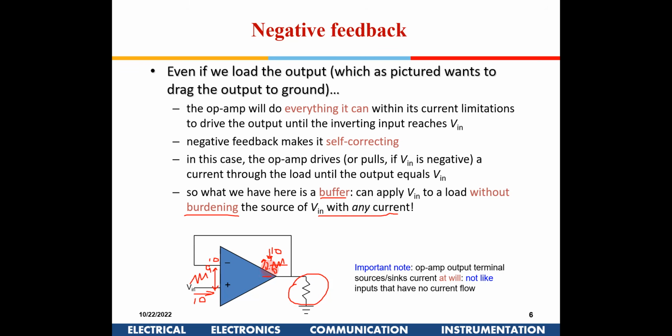But that cannot happen because the moment it starts slightly below, because of the high gain, again it will reach back to 10. So in an equilibrium condition, you can consider that these two voltages will be the same. If it is the same, then the difference is zero. Then the output tries to reach 0, but still the negative feedback is there, and that decreased value is again the difference we take. Then it is non-zero. So at equilibrium it will not be 0.